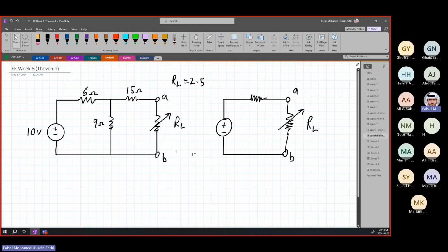All right? So the idea is to find an equivalent circuit where this is V Thevenin. This voltage is going to be the Thevenin voltage, and this is going to be your R Thevenin. So this is a specific resistor, which is an equivalent to all of this. And this is a specific voltage, which is equivalent to the voltage source there. And then using this simplified circuit, you can easily find the current going through RL using basic V equal IR equations. And you can find also the voltage across A. But how do we do that?